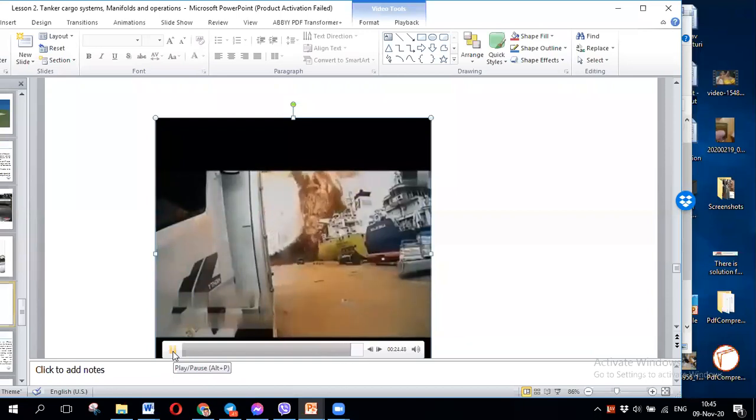And do you know what was the problem here? The duty officer was not taking care about the pressure inside the tank. The pressure was negative, and the tank was inerted, so nothing will happen inside the tank. But the pressure was negative, and the styrene monomer is a solidifying cargo and it solidified the PV valve.